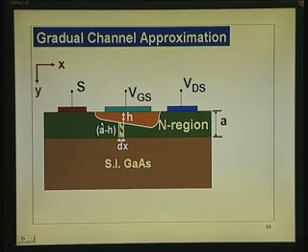In the linear region, the drop from drain to source, that is across this channel length, is small compared to VBI minus VGS. So, VBI minus VGS is the drop here; I have just put it here. Now, if the drop in this direction is negligible, what will happen to depletion layer width? Same. If this drop is negligible, the potential drop here and here will be the same thing. Now, if the drop becomes comparable to that, as you move from this end to this end, the drop across the depletion layer becomes more and more. Is it understood? If you do not understand, please ask, because this is where some difficulty can be there.